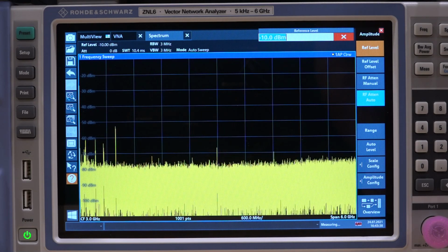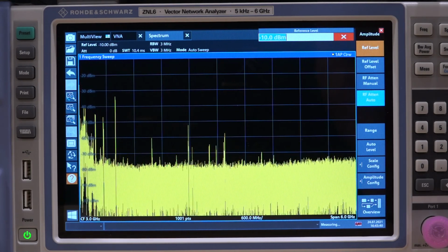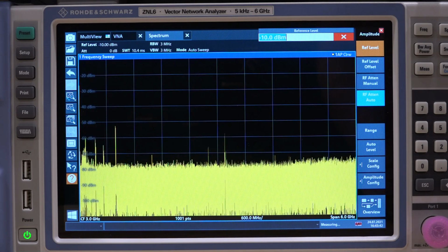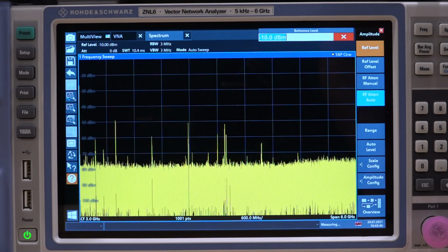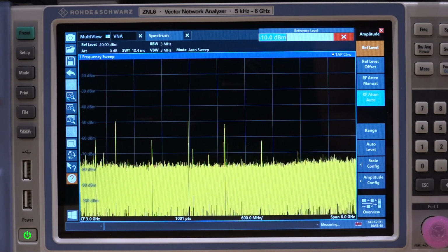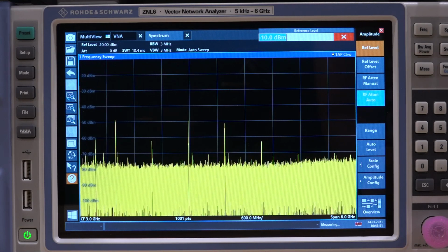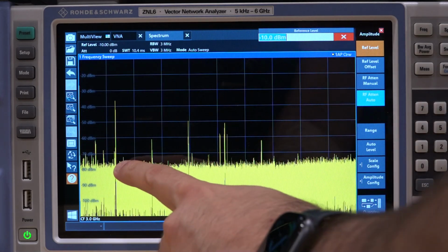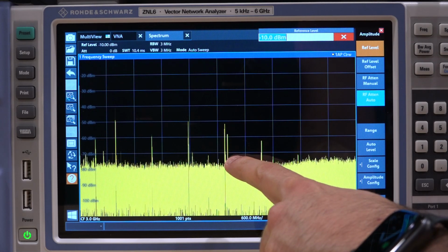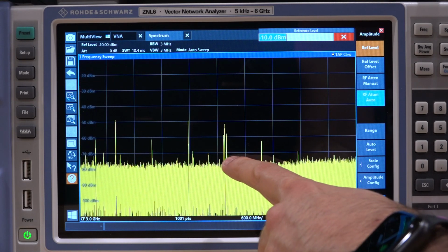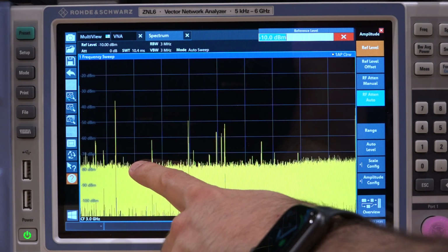Now the output of the divide by 4. That's a difficult spot to grab. Here we go. I have to get rid of all that low frequency noise. That means the ground is not connected. There you go. Okay. There are a lot of tones here, but it doesn't look good. Again, ignore that one, that's my wireless microphone. Here's the feed-through signal. That's our 3 gigahertz signal feeding through the divider. That's normal. But I don't see an equivalent signal around 750 megahertz, which is also moving around.